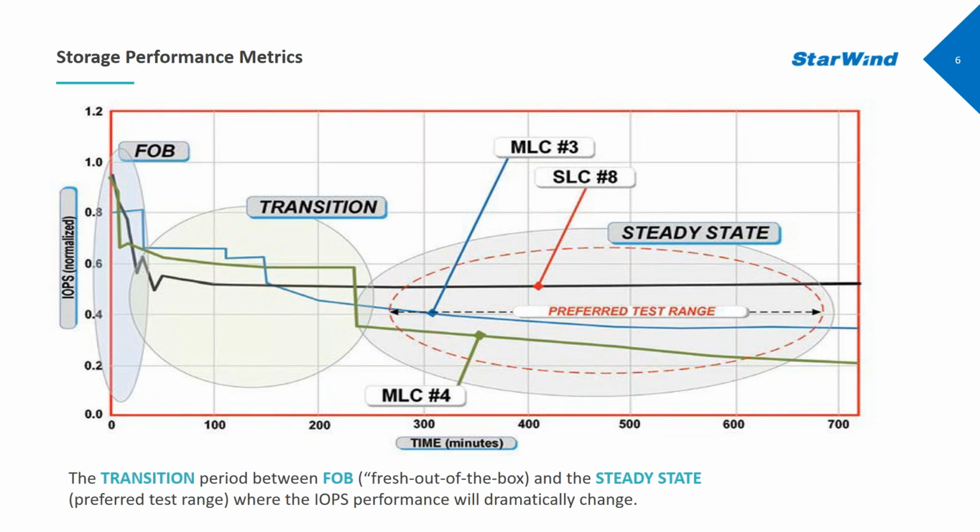Now, there are quite some differences between SSDs, and some of them are SLCs and MLCs. SLC stands for single-level cell, and the reference is the number of information bits that can be stored in each cell of flash memory. For SLC, this is 1 bit per cell. MLC stands for multi-level cell and can store multiple bits of information per cell. SLC-based flash has a write endurance capability roughly 10 times what MLC flash is capable of.